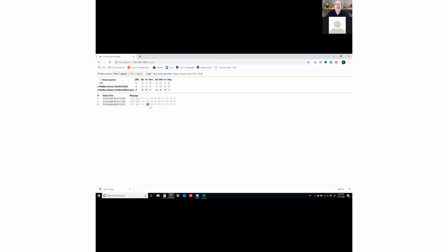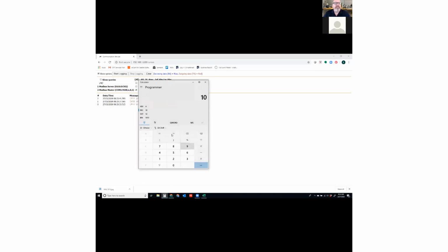Well, it's asking for Modbus ID 1. It's asking for function code 03, and it's asking for 00F4. And in 00F4, if I look at my hexadecimal value, that is register 244. So I know it's asking for register 244. It's asking for so many, but I'm not responding back. And I may not be responding back because it's a bad Modbus ID. The device is set up for a different Modbus ID. So that's a breakdown on the structure of these registers.